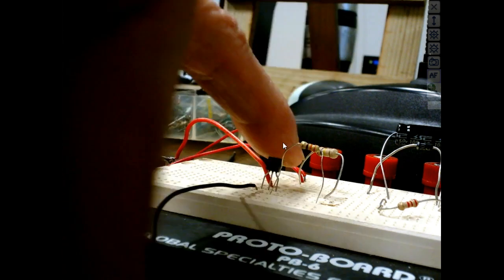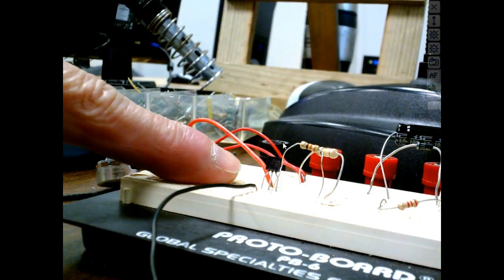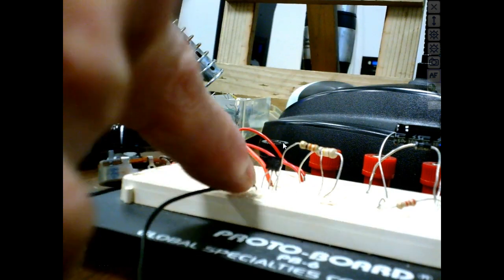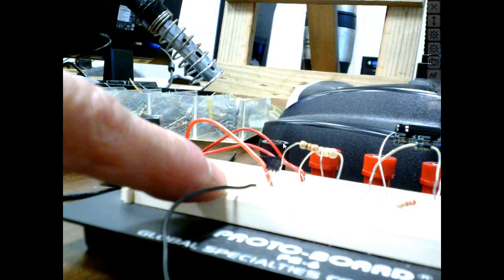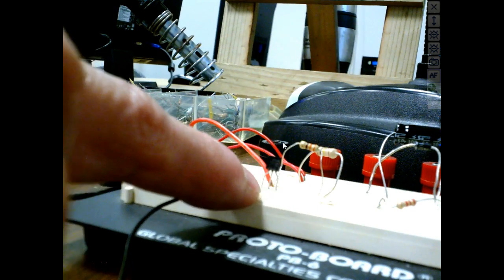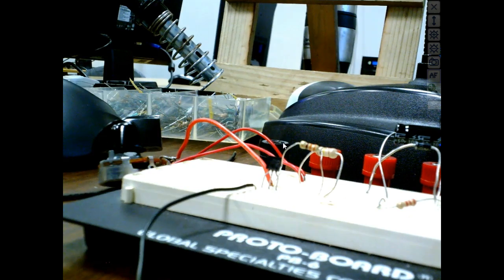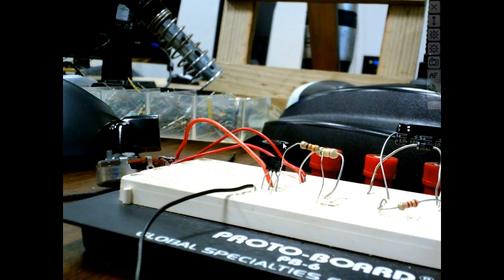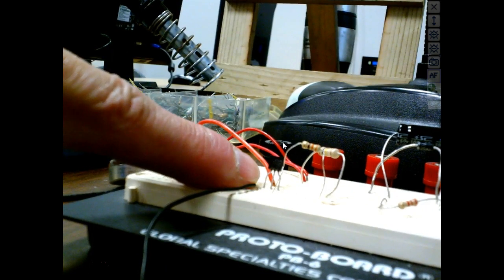So I'm using a 3904 transistor. This is the little TO-92 case, but this could be a voltage regulator. This is an NPN transistor, and if we look up the pin out, the pin out shows you the assignments of the leads. If we looked at the pin out for the 3904, it would tell us that the emitter is on the left, if we look at it from the front, so it's got a flat side to it.